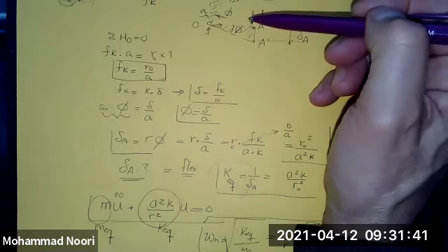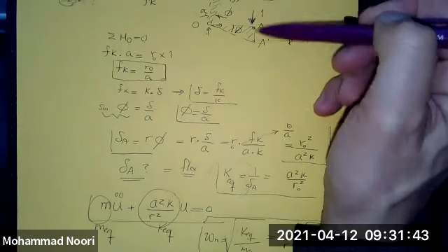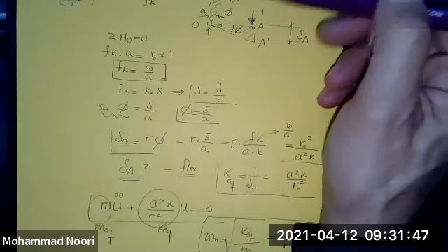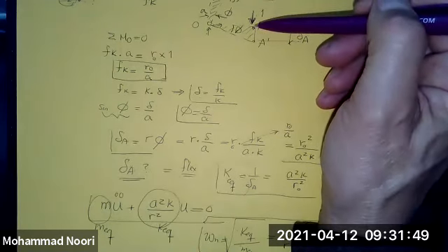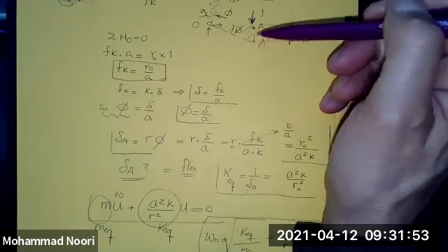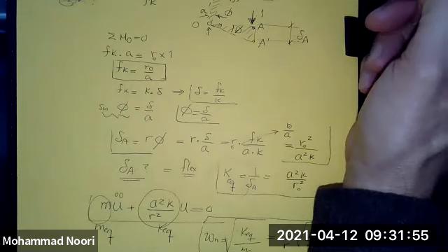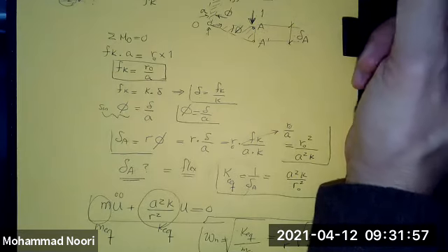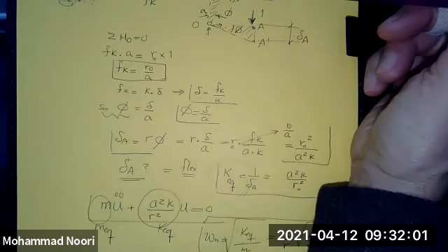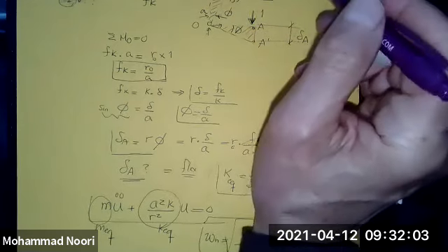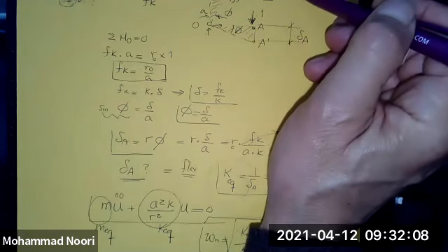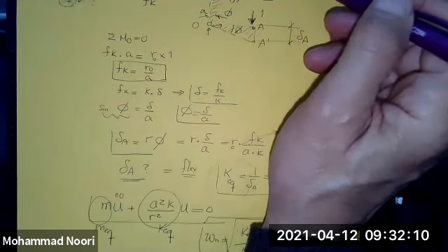What we want to find is the displacement at A due to this unit force, which would be the flexibility at A. And this is inextensible, so the displacement at A is the displacement of M. So the flexibility at A is the same as the flexibility that is resisting M.